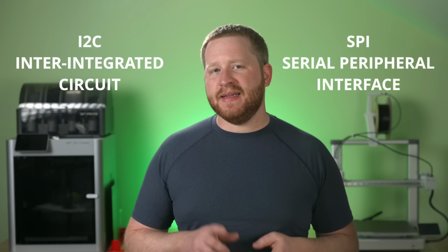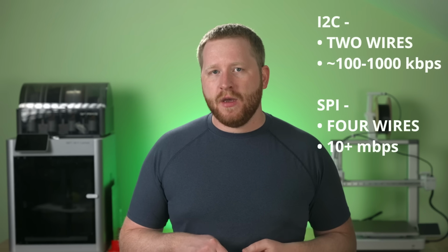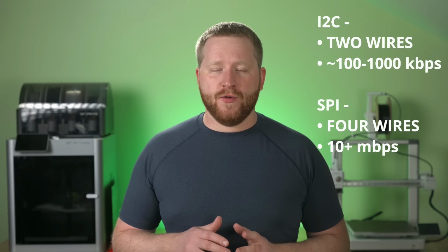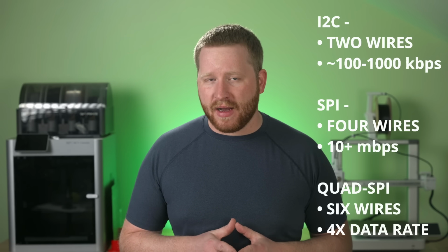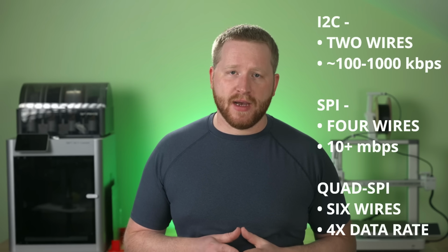The first is the communication interface between the display and the microcontroller. The two easiest options that most tinkerers are probably already familiar with are I2C and SPI. These are serial interfaces, so 1 bit at a time, with I2C generally being slower than SPI, but using less wires. Nearly every microcontroller has SPI and I2C peripherals, with some microcontrollers and displays also being capable of quad SPI, which has 4 data lines and 4 times the data throughput of traditional SPI.